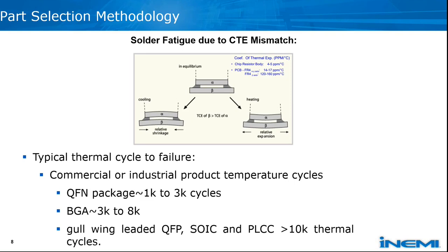Next. So we're looking at the typical thermal cycling tests, but we wanted to point out that in those tests, it can really extend the amount of time it takes to complete the test for thousands of cycles. In this slide, we show some examples with QFN packages up to 3,000 cycles, and I've seen a few more beyond that.